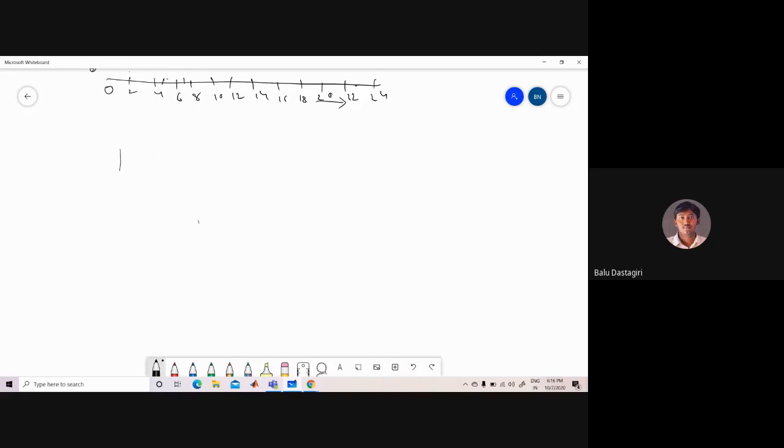So take a small circuit here. We have the inputs A and B. So this is the circuit. The AND gate is taken as G1, and the other labelled as G2 here. The AND gate has a delay of 2, 1, or else you can take a delay of 2, 2. The OR gate has a delay of 1, 2, for suppose. Here there is a wire, and the wire has a delay of 1, 1.